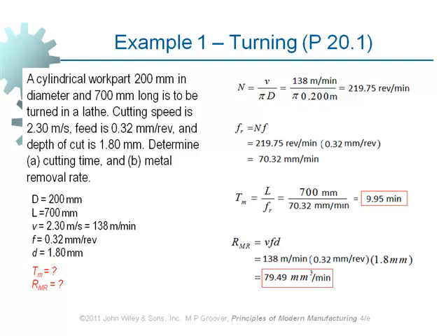The spindle speed is the number of revolutions per minute of the spindle. Cutting speed is the distance traveled on the workpiece by the cutter per unit time, which is totally different. Okay? Very different.